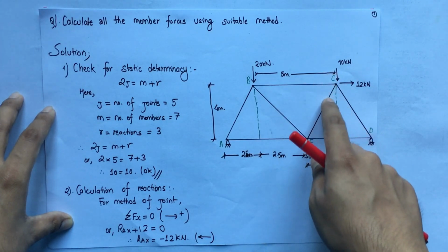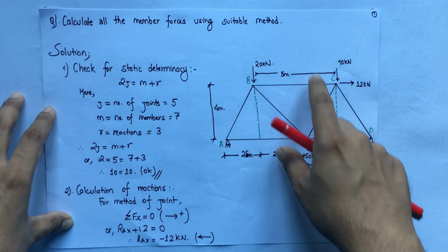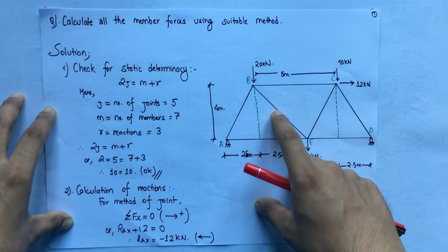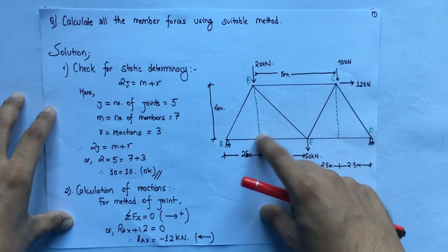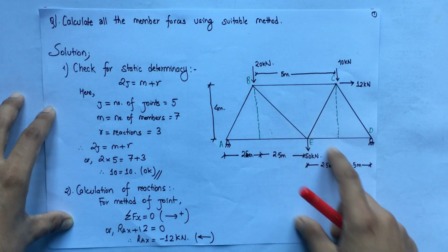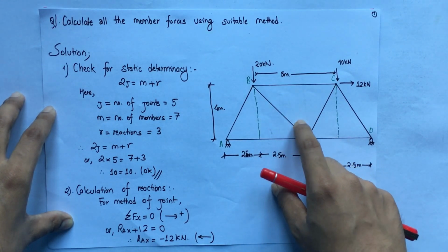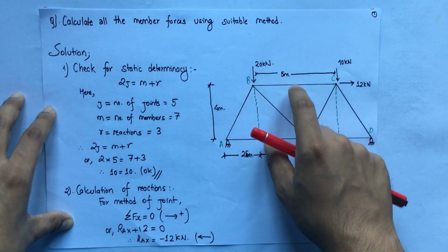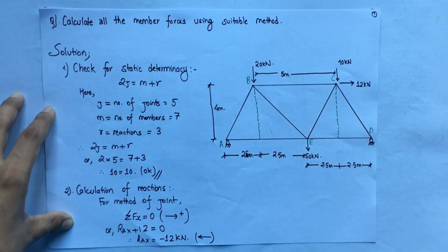All the external forces and reactions are applied only at the joints, and every member is subjected only to direct stress. For now we are assuming that the self weight of the structure is negligible in comparison to the load it carries.